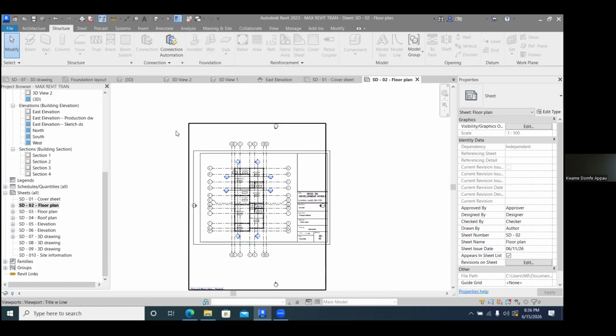See, this one also. Have you seen the one I'm asking you about? That black line around it is bigger than the sketch, the title block. Yes. The reason is the sheet: you've not scoped your view very well. When you add a scope box and then you scope it very well, this will be over.